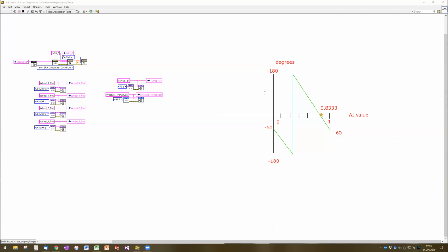Okay, and then the value that we care about when we do a calibration is this value right here. So that looks like it's right around 0.33. So this becomes the sensor value that we use in order to do the actual Swerve module calibration. And every time we change the calibration, what we're changing is we're moving, can I not select multiple things?